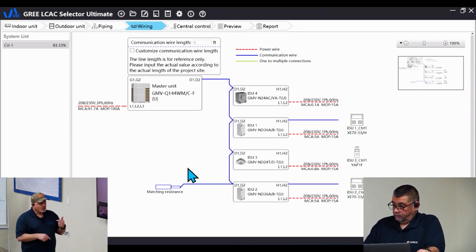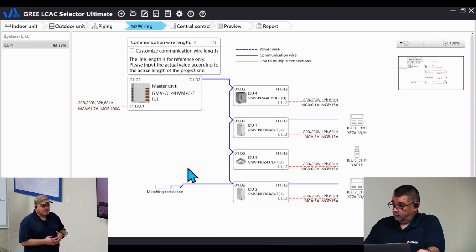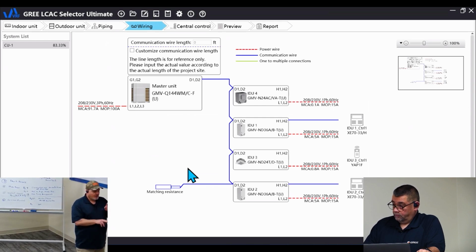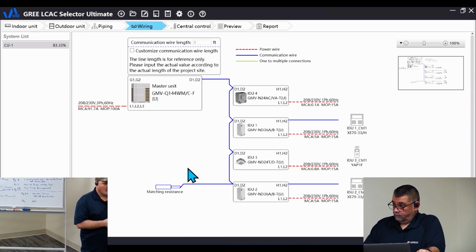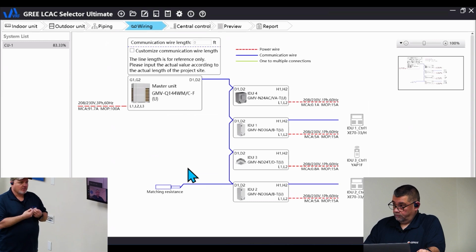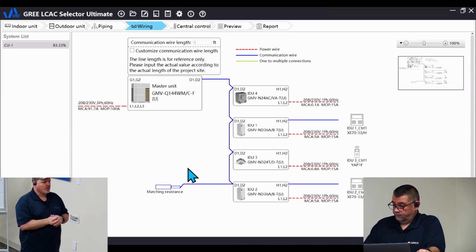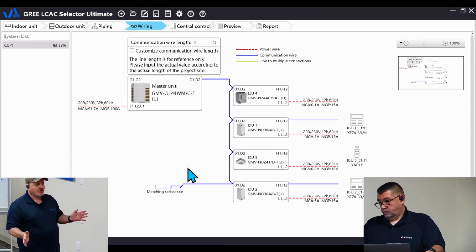So then your next unit going in, like we're going from indoor unit number 4 to indoor unit number 1, you're going to have screw terminals for all 4 of those wires. And then you take that ground wire and don't cut it off, fold it back on that thermostat wire casing, twist them together and then tape around both cables. That'll hold it nice and tight for you. And we know that ground's not touching anything else.